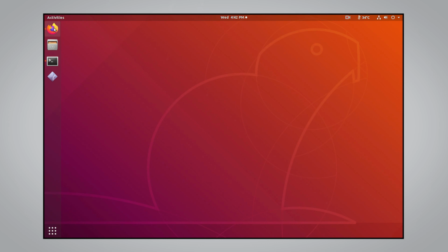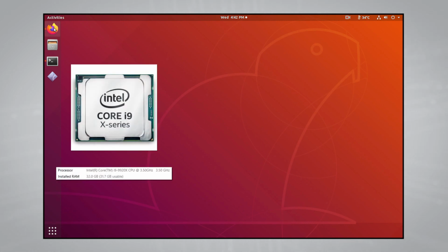One of the first questions that you may be asking is if you need to use Ubuntu Linux for everything I'm about to show you. No, actually, you don't. It's possible to run Xilinx tools on Windows or other distributions of Linux. However, when we get to generating other OS components like the root file system, the tools we'll need to use will have dependencies associated with Linux. So if you're trying to build all of the OS components, you'll want to use a machine that's running some distribution of Linux. Just for reference, I'm running an Ubuntu 18.04.5 OS on an Intel Core i9 processor.